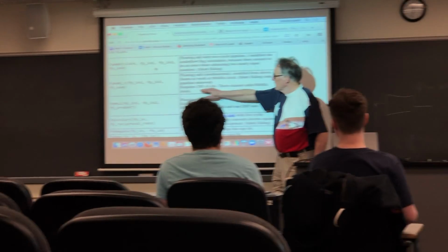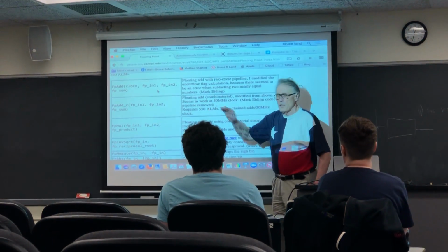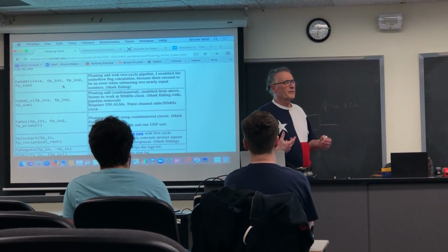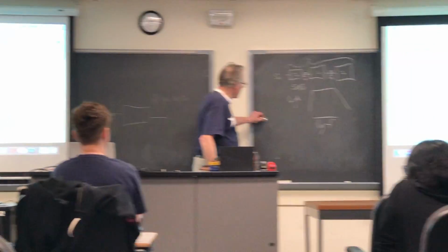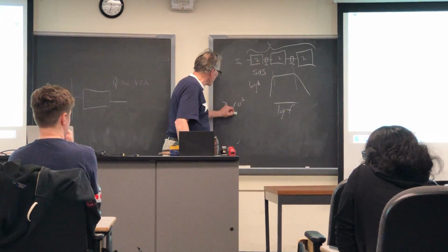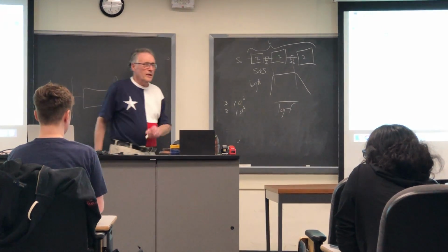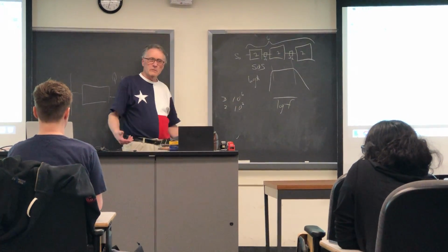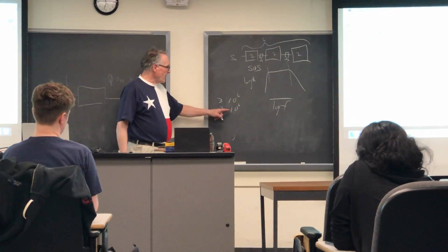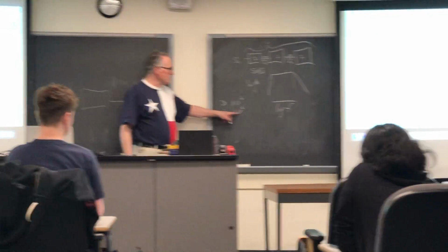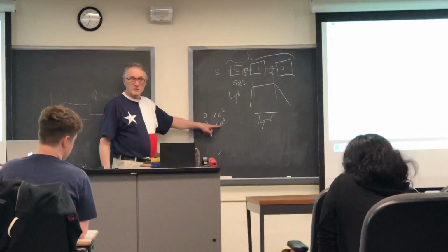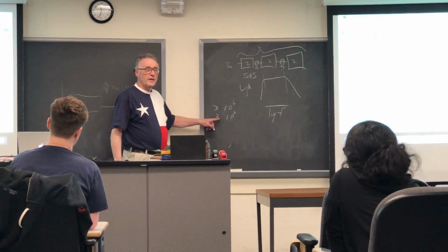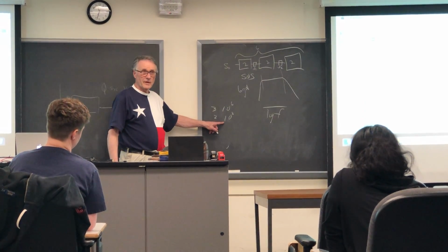Most of the logic here for adding comes from the fact that if you have two floating point numbers, 3 times 10 to the 6, 2 times 10 to the third, to multiply them is easy. You multiply these, you add these, you're done. To add, you have to normalize these to the same exponent, do the add, and then renormalize to the correct value.